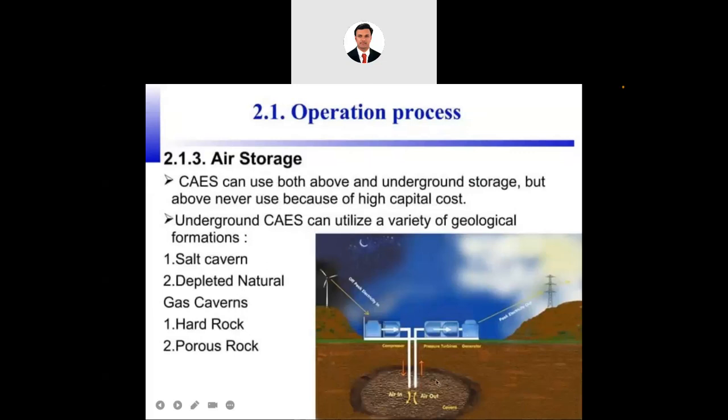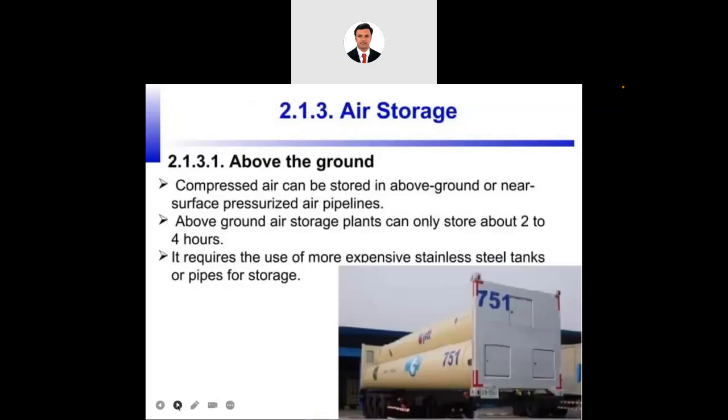We are using different caverns to store this energy. We can store the compressed air on the ground or inside the ground, but the main disadvantage of storing compressed air is that the capital cost of storage is very high. For that, we are generally using salt caverns or depleted natural gas caverns to store the compressed air inside the earth crust.